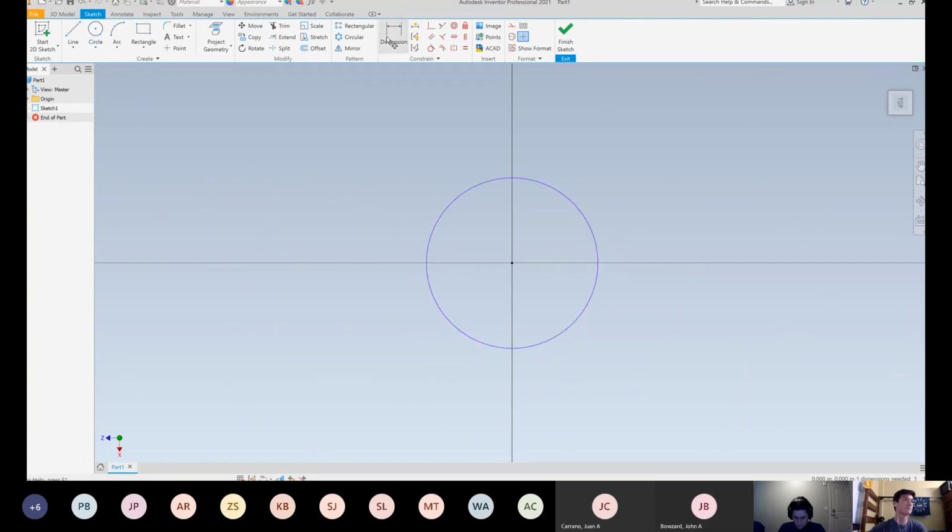Well, actually, oh, you see the arrow here? That means it's the diameter. If it were radius, the arrow would be between the edge and the center point here. So we'll set it to 3/8 inch. And you can define it with decimal value or fraction, doesn't really matter.